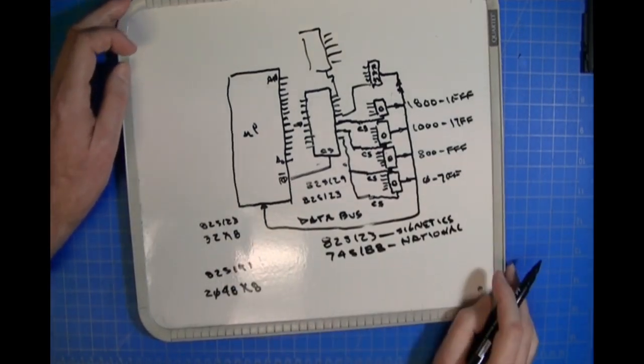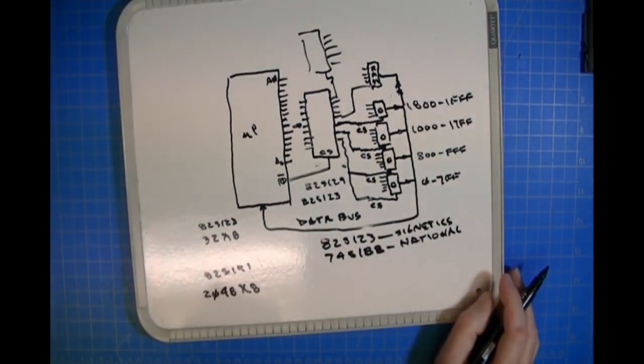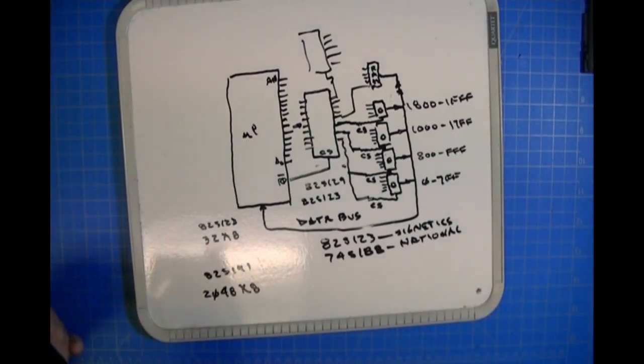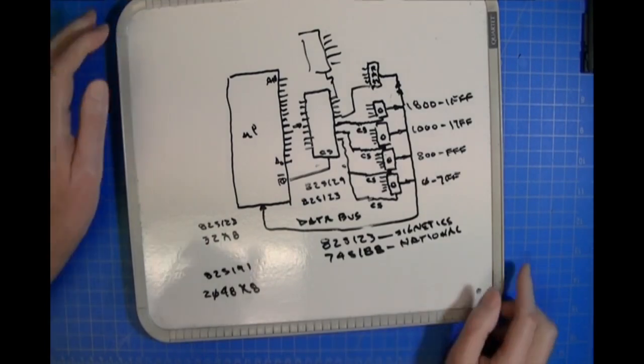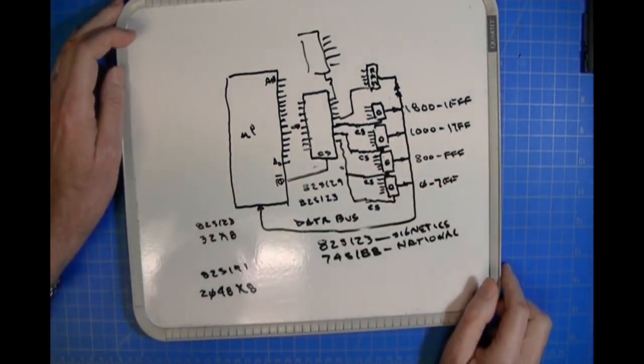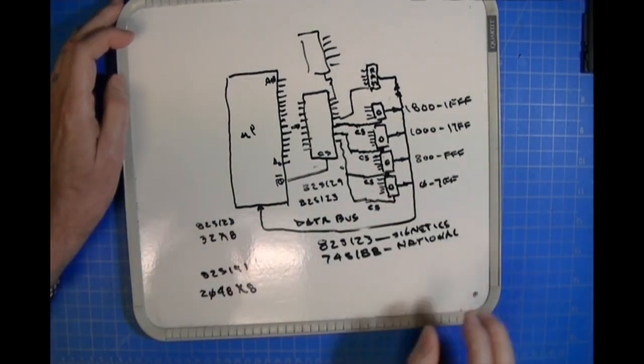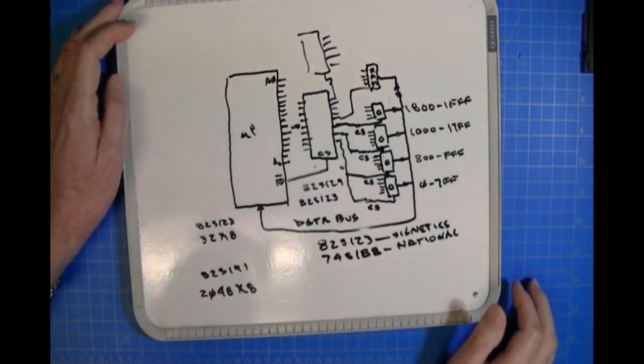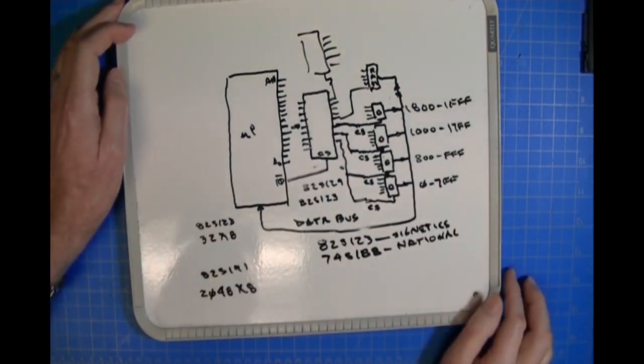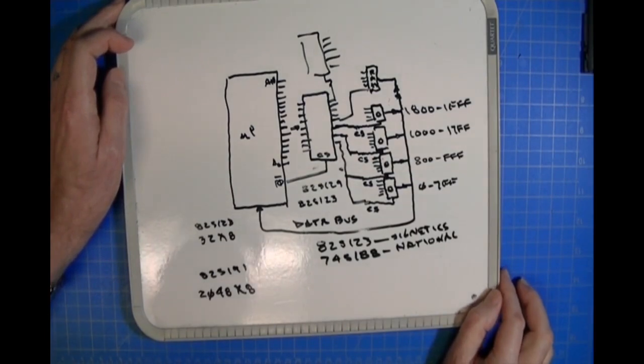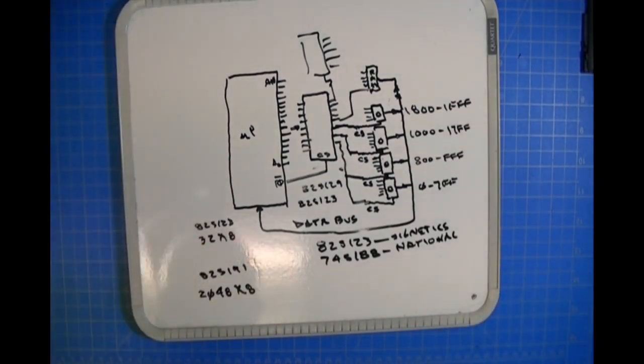Now, different manufacturers got into the bipolar prom business, and another problem with bipolar proms is that they all read the same way, meaning they've all got input lines and output lines, chip select, and all of that. They don't program the same. Everybody, when it came to programming bipolar proms, went their own way. Signetics and National had the two most common programming algorithms.